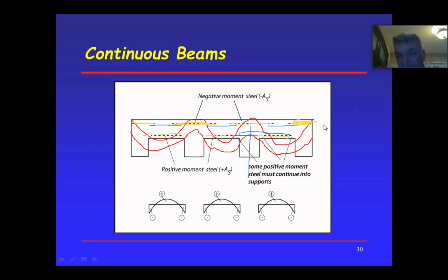From this side, this is the exterior support. First interior support from this side is this. So that's going to be the biggest moment. Due to symmetry, this moment is equal to that moment. Okay, and I will draw a moment diagram in a second. Any question before I erase these lines? Okay. So let me clean this beam.